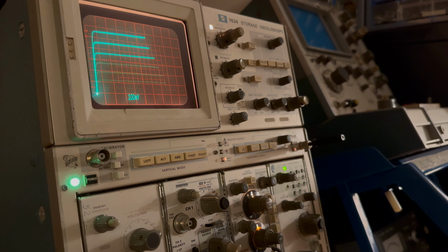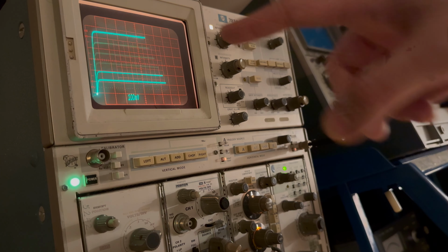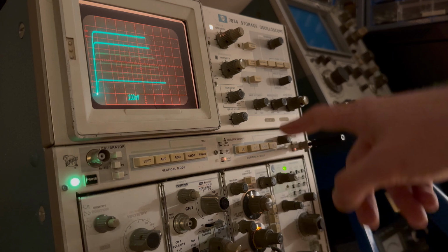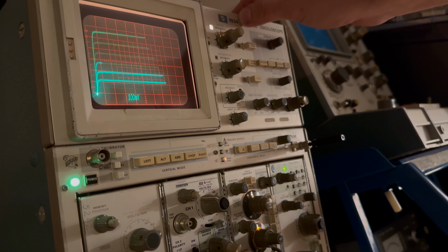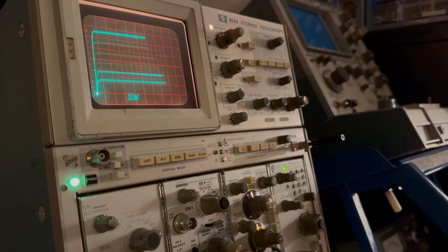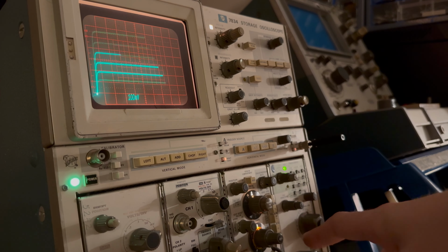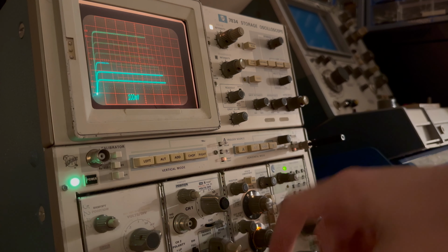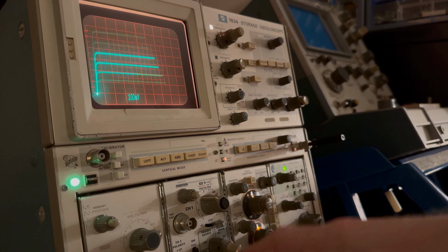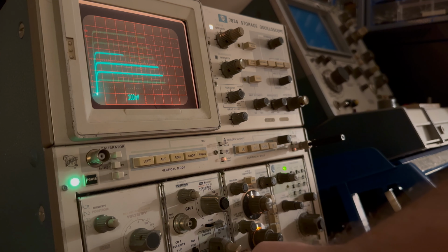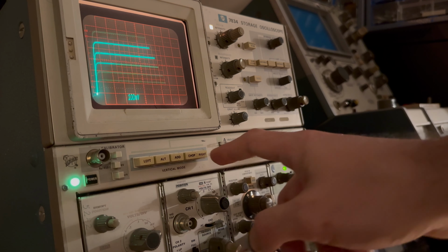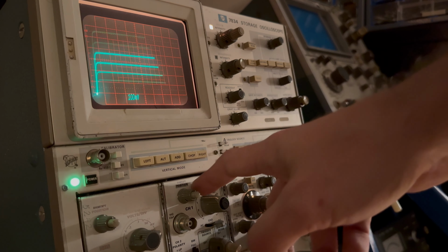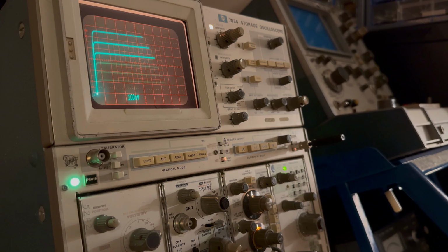Okay, so as you can see, the curve tracer is plugged into a horizontal slot in this mainframe. This is a 7834, and you can't really see it, but the cable is going from the output, the BNC I was showing you, to one of the inputs of this vertical. This is a 7A26. It's a 200 megahertz plugin, but that's completely irrelevant.